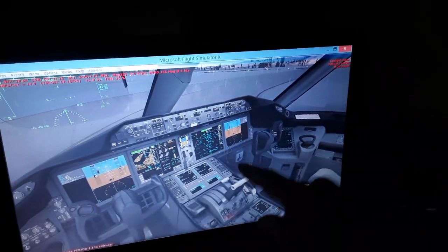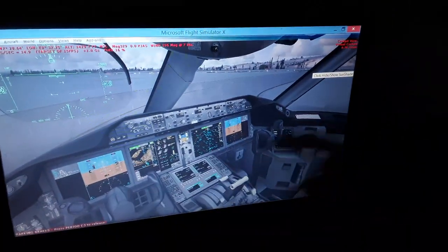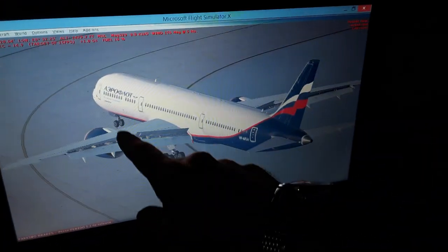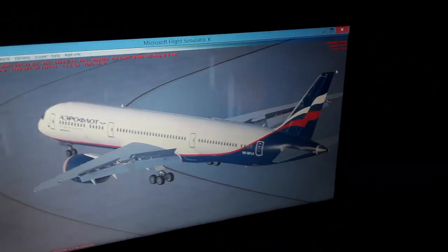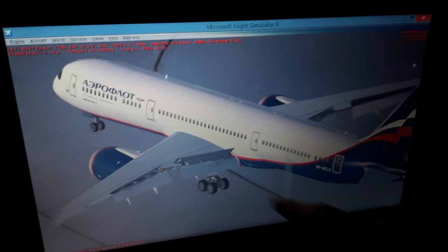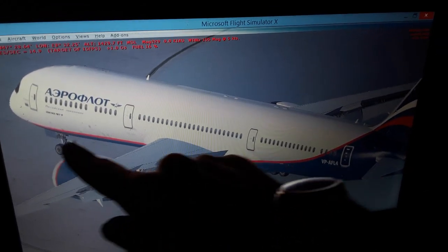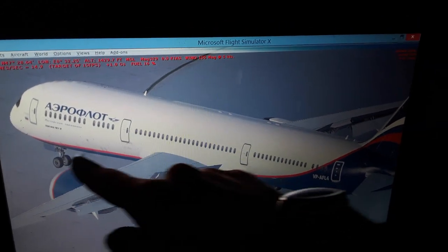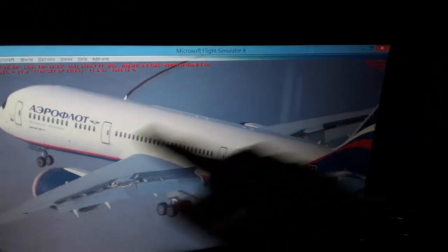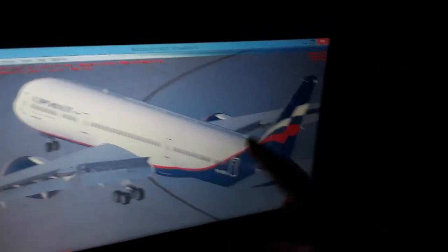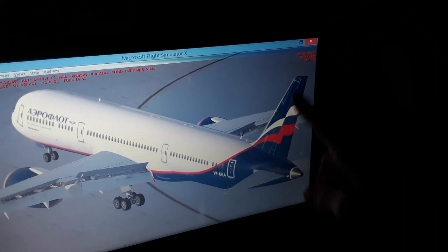Both rudder pedals in the Boeing, the Airbus, the Embraer aircraft, and the CRJ are interconnected when we fly. Also, we'll show you the rest of the controls. We also have the nose wheel, which is deflected on the ground together with the rudder. So the nose wheel is deflected in left and right turns, 76 degrees left and right, for nose wheel steering on the ground, in takeoff and in landing. 76 degrees from 0 up to 45 knots, 45 nautical miles per hour, or 72 kilometers an hour. Then the rudder becomes more aerodynamically effective, as you can see.